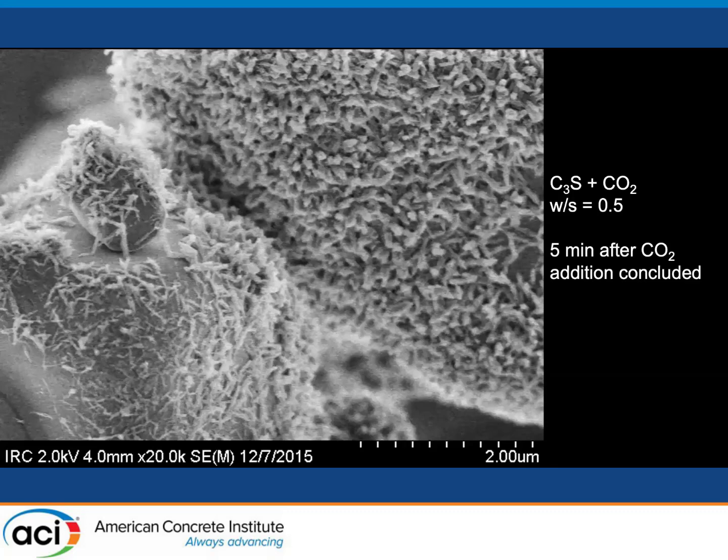If you look at a system like this a few minutes later, in this case it was a slightly different study, again tricalcium silicate, this time the water to solids was a bit lower, we can see in the CO2 activated system that we're getting a lot more of a gel phase forming even at 5 minutes. We do not necessarily have the reference concrete in the presentation. I should have put the paper reference on this slide, I apologize, but this is a net difference in the amount of products and the timing of these products versus the reference case.